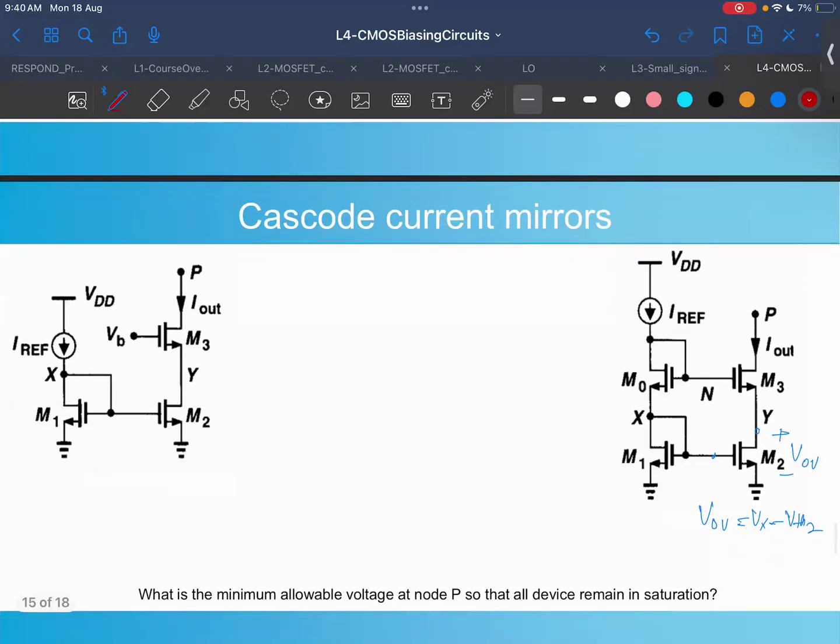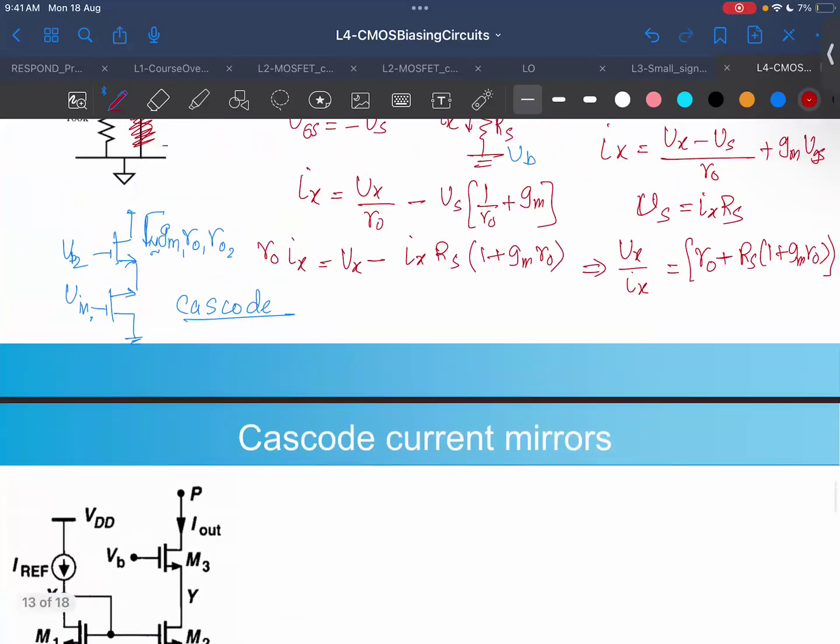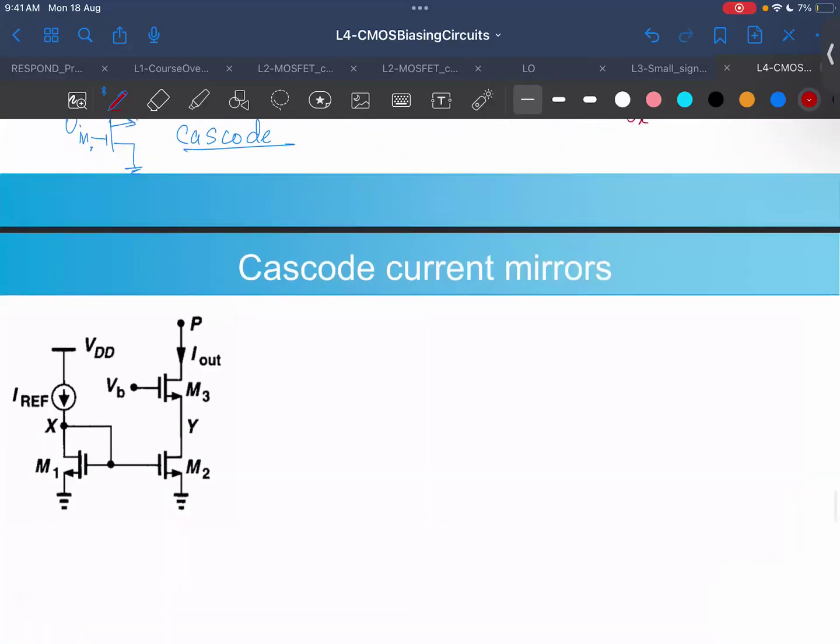Okay, so this short video is to continue our discussion on current mirrors, right? And you were given a homework, if you remember. We were talking about the cascode, the benefit of cascode, right? So basically, it's the resistance which you have from here, R naught, which increases, because there is a factor multiplied by gm and RO in the resistance. So that's why you get the effect.